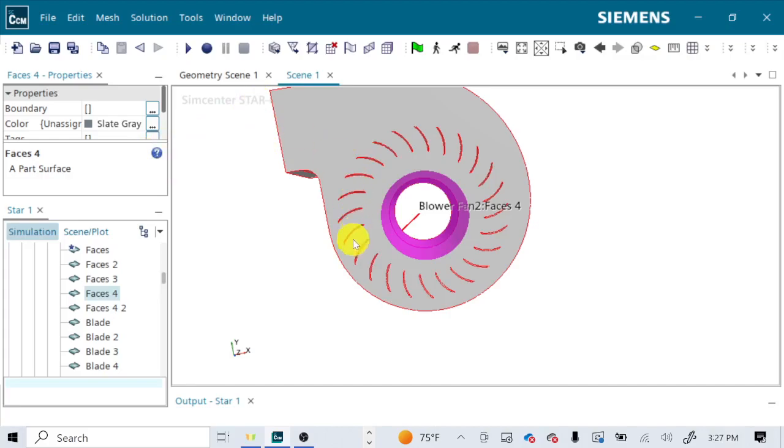It's worth noting, this is a little bit of something that took me off guard. If you see fans that look like this, sometimes the blades are curved this way, which would seem logical, right? It's almost like they're shoveling air out through that outlet, right? They're sometimes sloped back the other way. They are reverse curve fins. Or sometimes they're just straight fins.